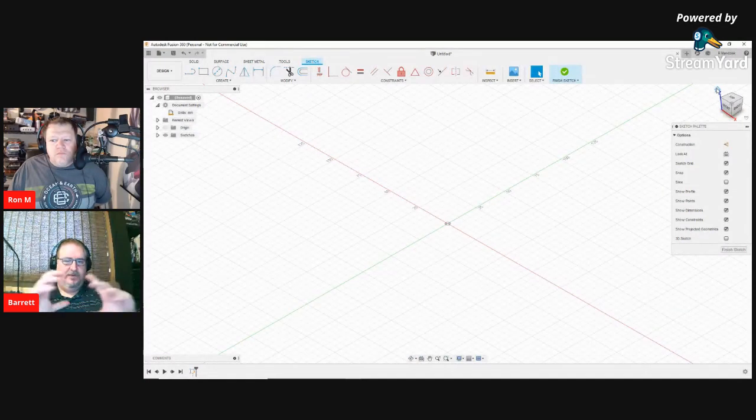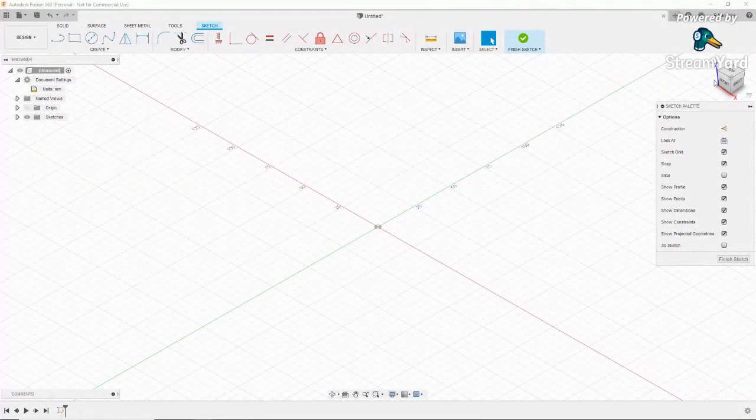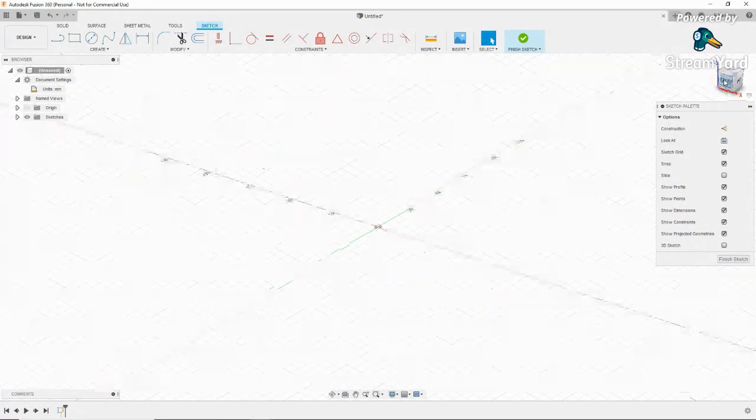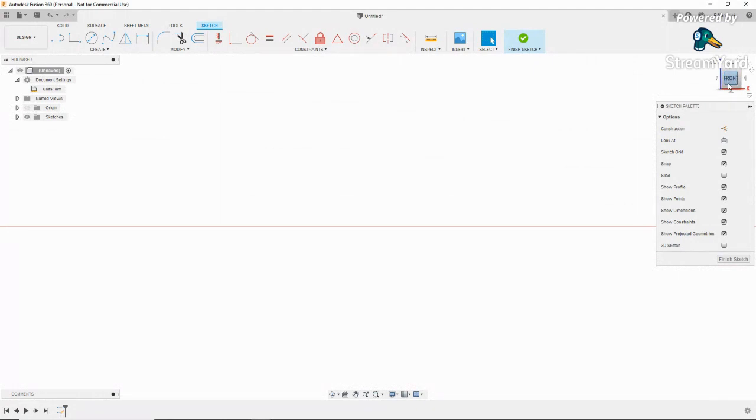That's going to show you the model from the side and the angle. But if you look at that ViewCube up there, you can click on any side of it that you can see and bring it to you, including the corners. So if I click on front, it'll snap you to the front view. Now, if you notice, there's also a little drop down to the right of it.